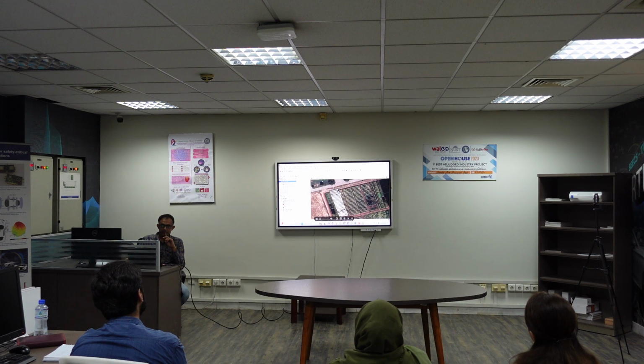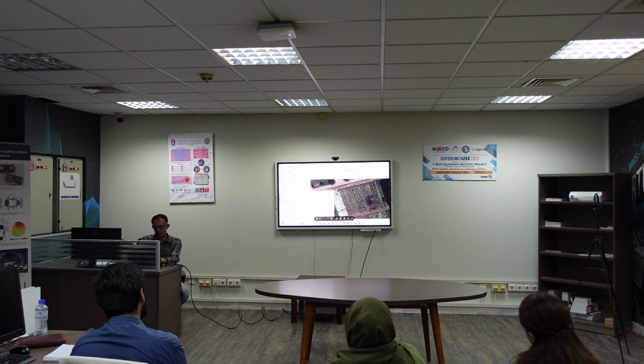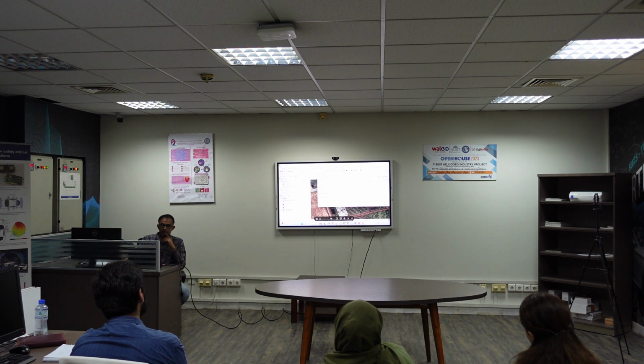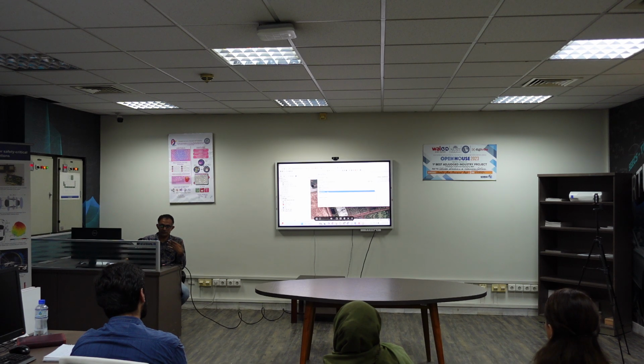Now, what we want is the mean or some sort of joint statistic of those plots as a single value, so that we can better comprehend it and base our analysis on that single value. For that, there is a tool called zonal statistics. Basically, it requires the input layer, which would be the plots that we have generated for which we want that NDVI data. Then there is a raster layer that is required. Then the band for which the statistics are required, but because it is single band data, there is no point in that. Again, the output column, we can say that we want NDVI.